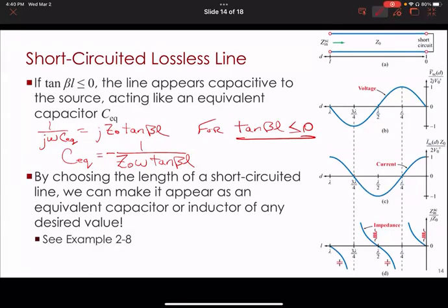All right, so now you've got lots of options there. And so then you'd start thinking, well, you have to take into account how much they cost. What's their physical size? Will it fit on the board? Is it going to get in the way of other things? So you have to think about all those things. But one thing that you definitely have to think about is you'd have to go through the data sheets and make sure those capacitors work at the frequency you're using them.